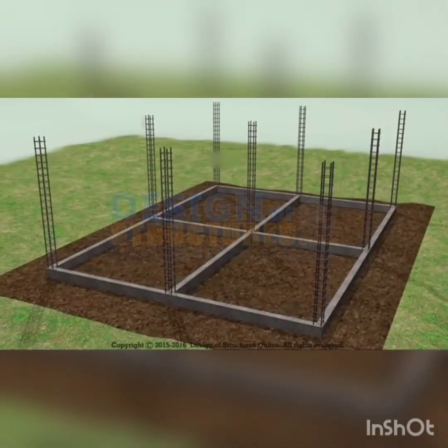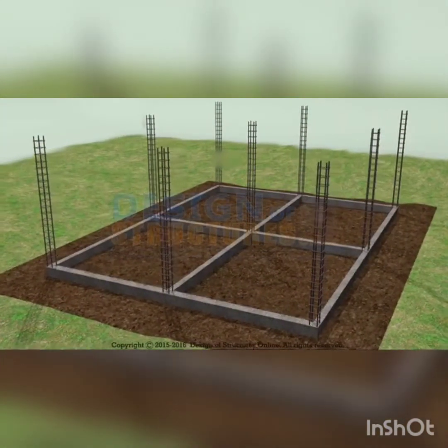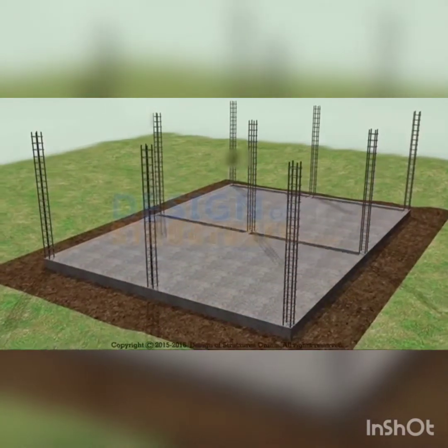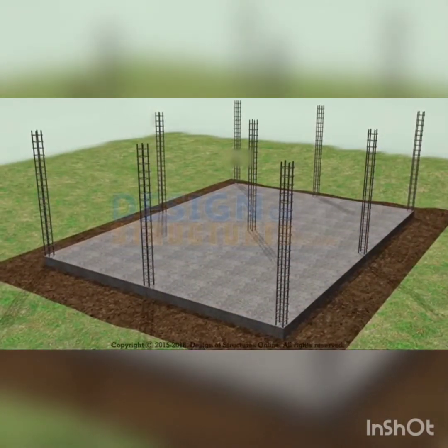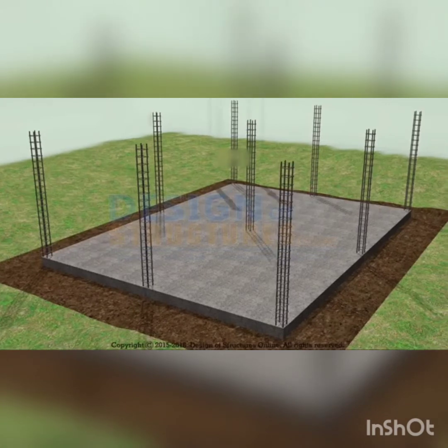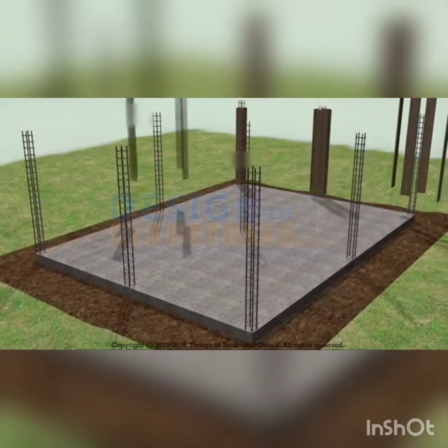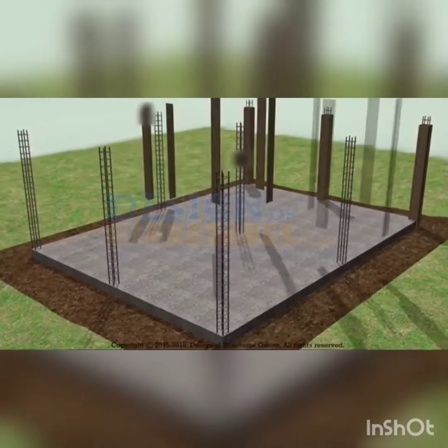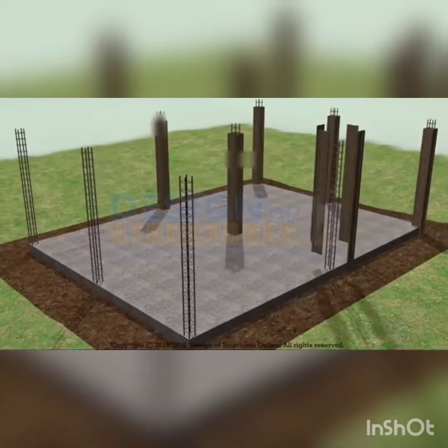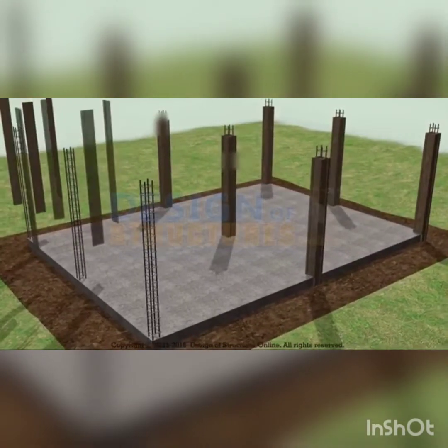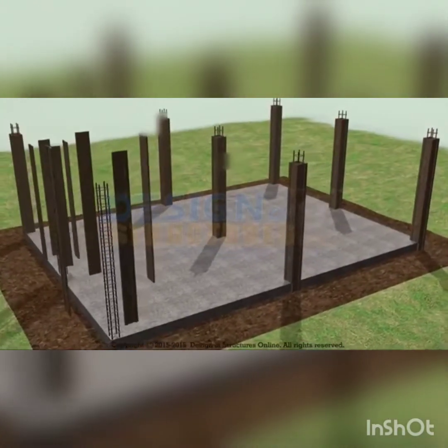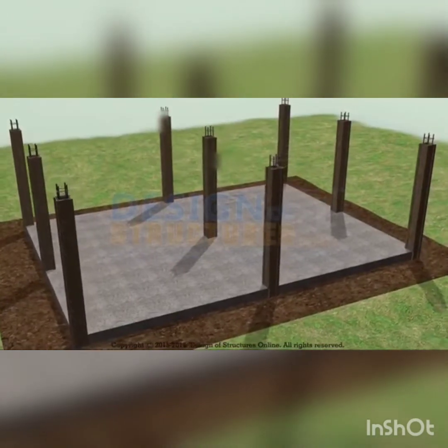Slab concreting. Grade slab requires no reinforcement as it's resting on ground strata itself. Top of plinth beams and grade slab should be at the same level. Column shuttering. Column shuttering should be rigidly constructed and efficiently propped and braced both horizontally and vertically, so as to retain its shape. The shuttering should be set accurately to the desired line and levels and should have a plane surface.